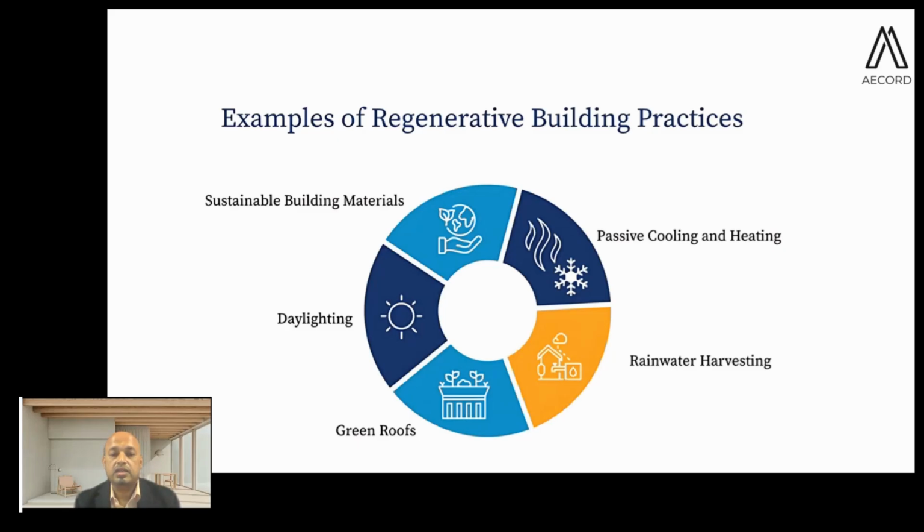So when I say air conditioned, it can be heating or cooling. When you replace your air conditioning with passive methods of natural ventilation, of cooling, or trapping the heat inside and gaining heat from the sun and trapping it into the building, hence reducing the heating energy, you can save anywhere up to 40 to 60% of your annual air conditioning load. When I say air conditioning, it's both.